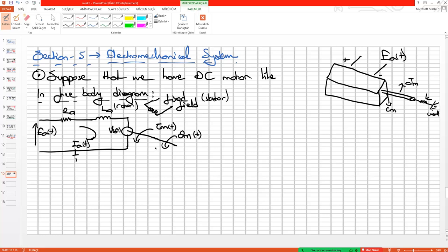Okay, and so we can combine it using the transfer function domain or the Laplace transformation in order to represent the E_a(s) as given to our system, which is known as the plant G(s), and then we will have the theta_m(s). Okay, this is the advantage of system dynamics. We can combine the two separate systems, electric and mechanic, into one form. Okay, system dynamics.